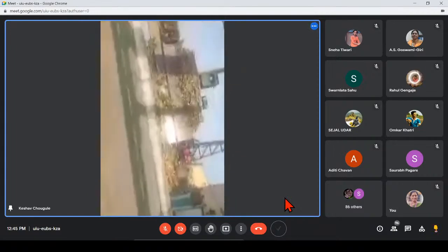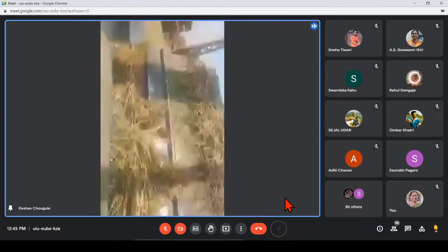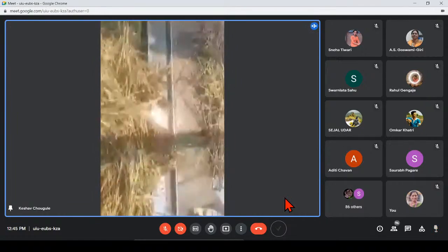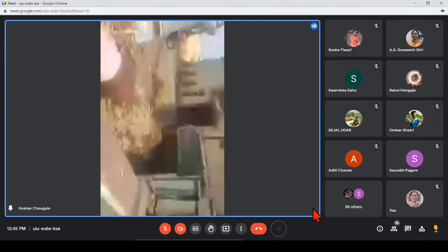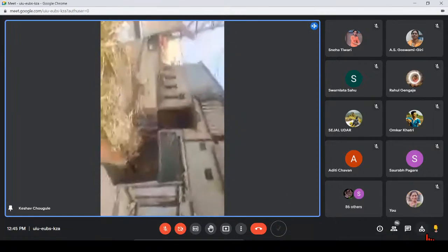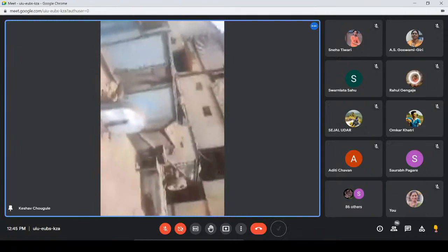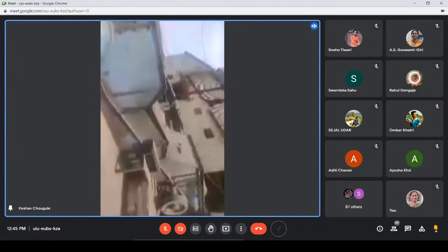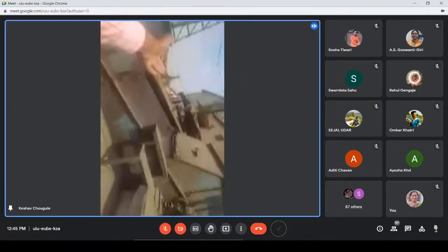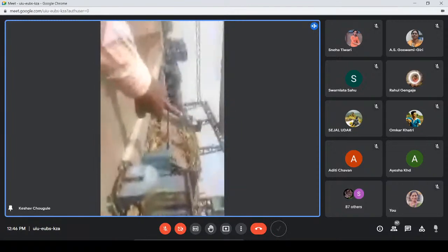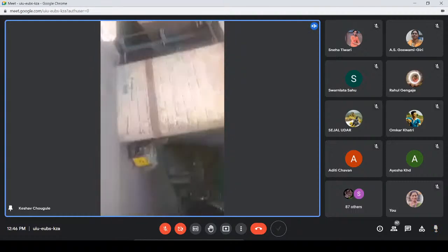See, these are the sugar canes which fall on this feeder of the sugar carriers, and that drops the sugar cane from the feeder, which is cut into small pieces. See, that is called the sugar cane crusher. The sugar cane crusher crushes the cane into small pieces, and the roller mill is driven by a 250 HP DC motor, which is at the backside of these technical parts. All the processed sugar cane then moves towards the next side of the industry.